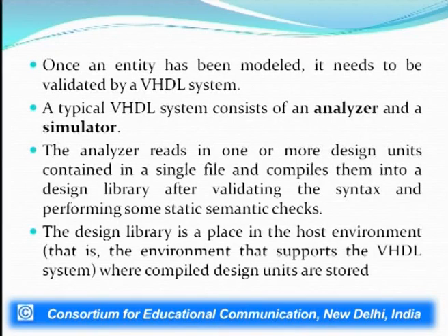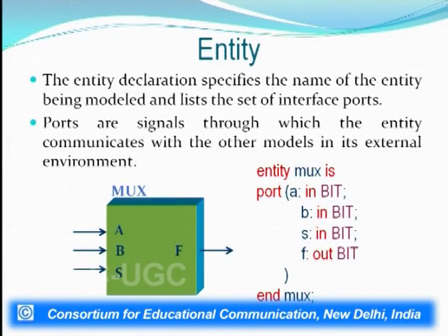Now once an entity has been modeled, it needs to be validated by a VHDL system. A typical VHDL system comprises an analyzer and a simulator. Now what does an analyzer do? It reads in one or more design units contained in a single file, compiles them into a design library after validating the syntax and performing some static semantic checks. So it is basically an editor kind of function it is doing. It is going to see whether everything is syntactically and semantically correct without going into the technical details. The design library is then placed in the host environment, that is the environment that is going to be supporting this VHDL system, where the compiled design units are stored.